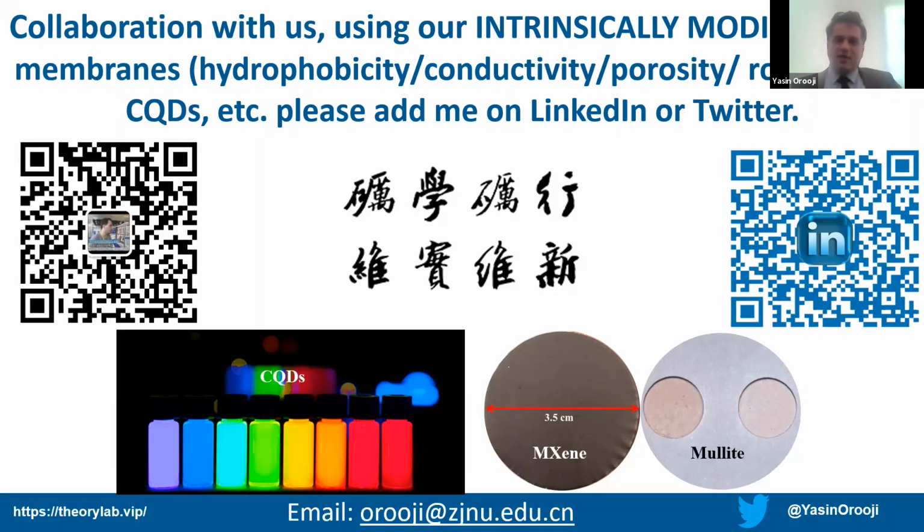And by adding a sensor at the top of the membrane, we have another parallel module which could simulate the actual fouling in the industrial module. You can get the alarm for cleaning in place even automatically.